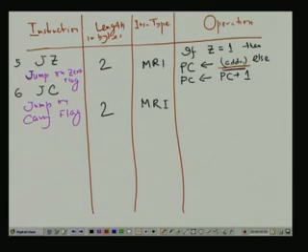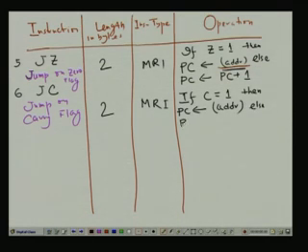Else, that means if this condition is not satisfied, that means 0 flag is not set, then PC is PC plus 1, that means it will continue, that means program counter will be incremented by 1, the next address. Similarly, JC means jump on carry. So, here also if C equal to 1, then PC is the new address where it will be jumped, else PC is PC plus 1. So, these two are similar types of instruction, only the condition checked is 0 flag or carry flag.